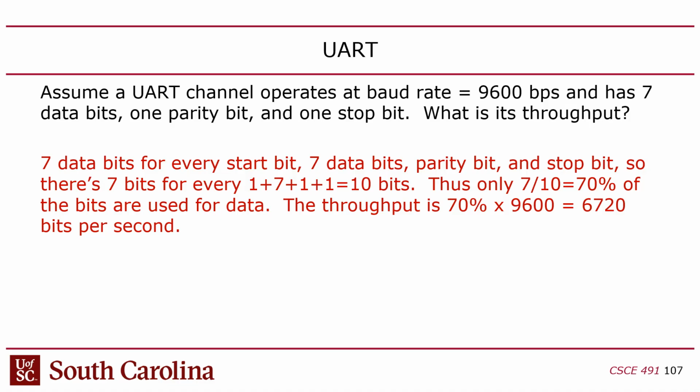Now, the only case where you're going to try to actually use all the throughput is if you're programming an Arduino or something, right? Usually you don't use all your throughput because, as I mentioned, UART's usually for terminals, where you're typing. So throughput is usually not a big deal unless you're doing some kind of bulk data transfer, like when you download your code to the Arduino, which, again, would be better to do over SPI, but there's no way to put SPI on top of USB, so that's why UART.